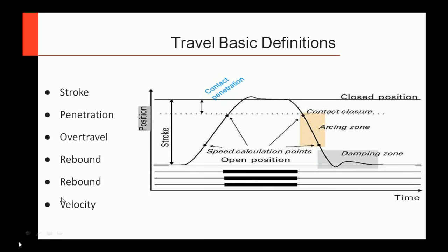One thing I'll mention here is velocity. Velocity is very important. Why you want to measure velocity is you might have a circuit breaker that maybe the trip coil is bad or something's wrong with the coil. So it might operate slow. Instead of operating in 20 milliseconds, it might take 50, 100 or something because it's bound up. But then once that coil releases the trip latch, as long as your velocity is okay, it'll have the energy to interrupt that circuit breaker. I'm sorry, to interrupt that arc.